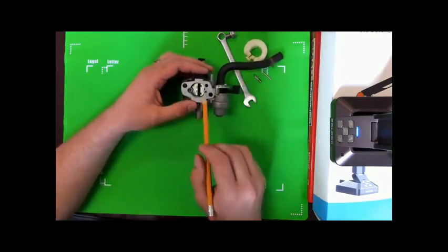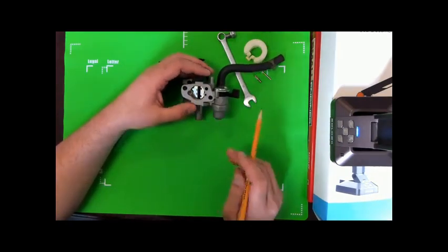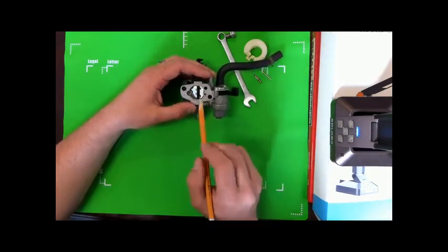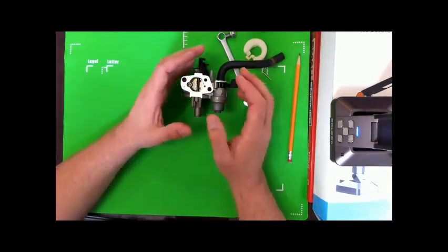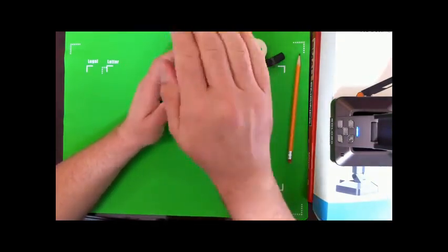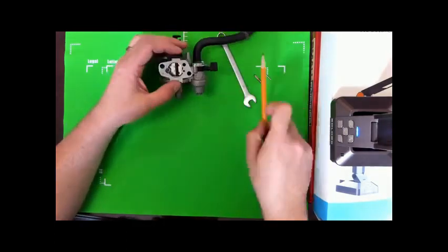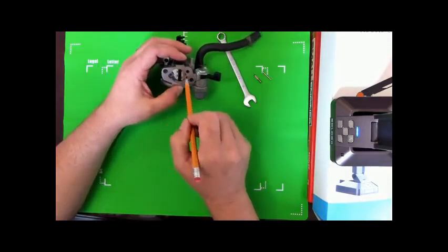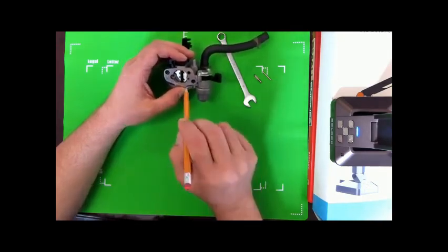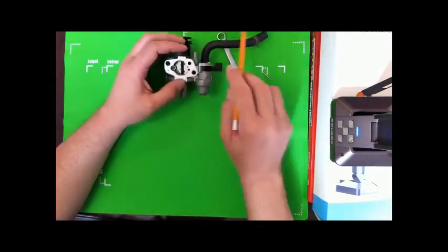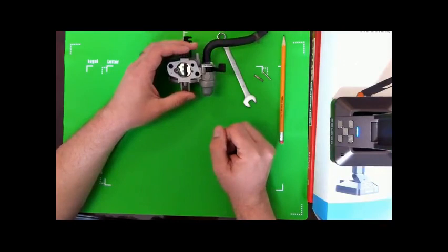So if we engage the choke, now you can see that this choke plate is restricting airflow through the main barrel of this carburetor. Remember what's going on when we pull that starter rope, we're starting to engage the 4 cycles of the engine. That piston is going to move down the bore and create that vacuum. Now we have made these ports, called the high-speed port or high-speed jets, the only area for air to go through the carburetor, and it's going to move faster, and therefore it's going to vaporize fuel more efficiently.